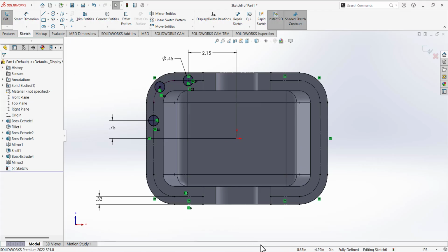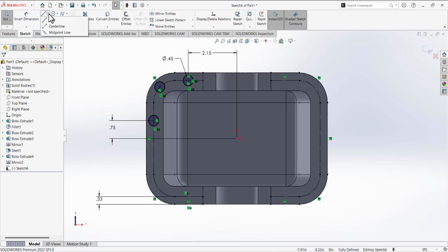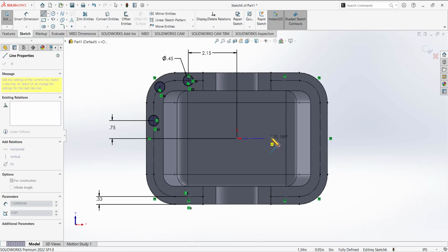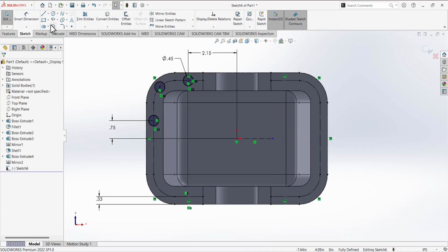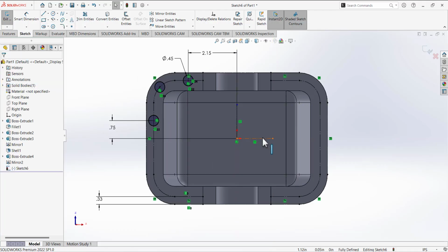As you can see in this sketch, we have these three tabs, and on the other side, we also have these tabs here. So three in this side, three in here, three in here. So we are going to use the mirror command, and it will save a lot of time for us. So draw two center lines, one vertical like that, and again a line, this one vertical, and this line horizontal.